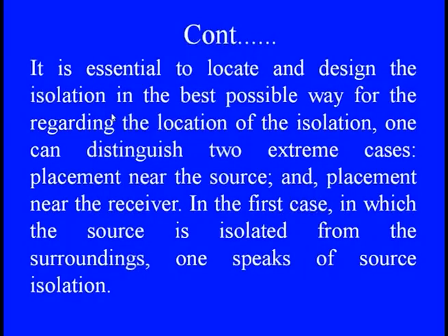So, that is why it is very important to locate and design the isolation in the best possible way, regarding the optimum location of the isolator, because through that we can put it in such a way that the vibration is not transmitted through this solid media and does not disturb the other equipment as well.